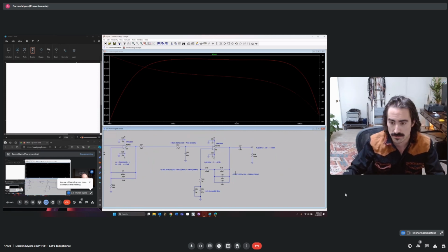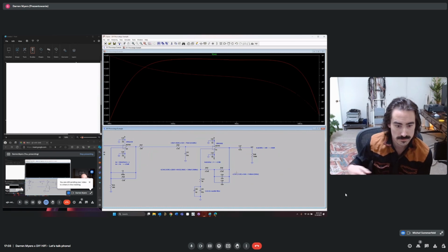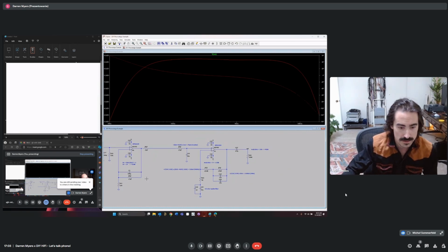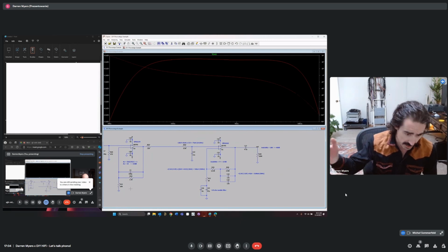Yeah, and also in the first stage, we have the resistors R22 and R21, but we cannot bump them in value to facilitate a reasonable capacitor, because it will eat our noise performance, right? That's right. The dominant resistor for noise is R21, because in noise we're looking at R22 in parallel with R21, and R21 dominates in that case.